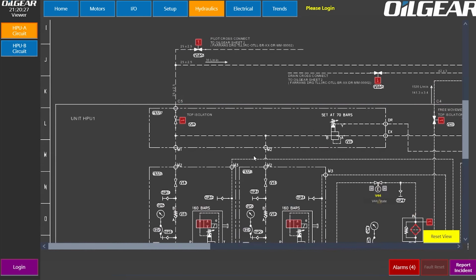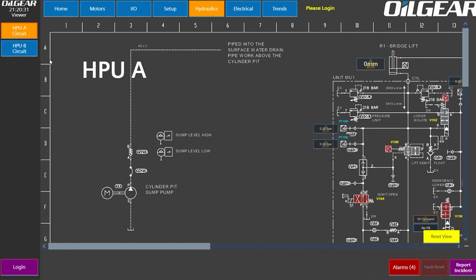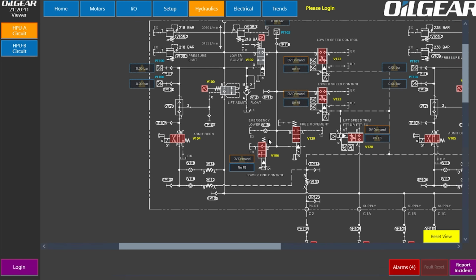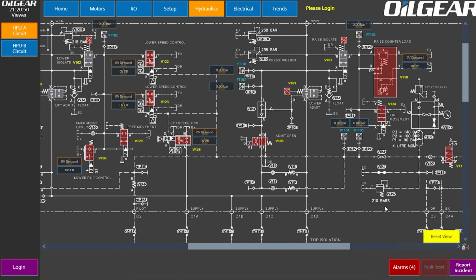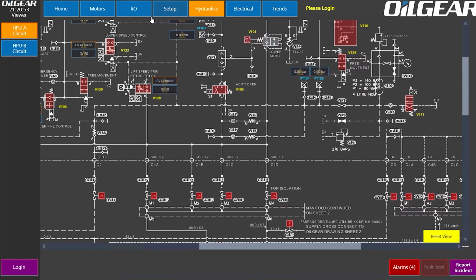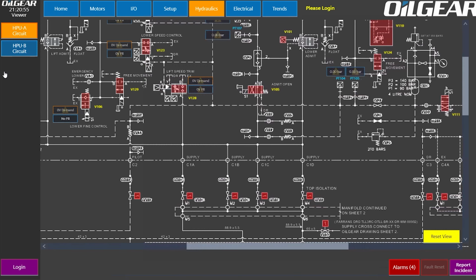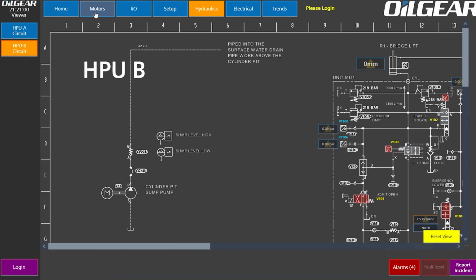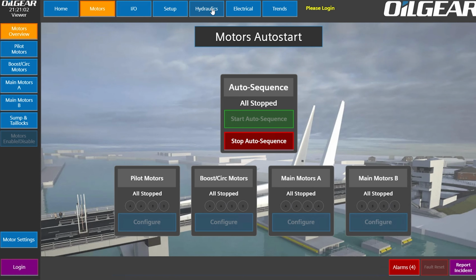And then what I've done here is a screen window, which I guess will be the same on whatever HMI software you're using. I've got a screen window that sits here, and this image is a big, massive 6,000 by 6,000 pixel image, whilst my normal screen is 700 by 1400, for example. This allows me to pan around inside the screen window without moving the whole HMI, keeping the rest of the navigation the same, etc.